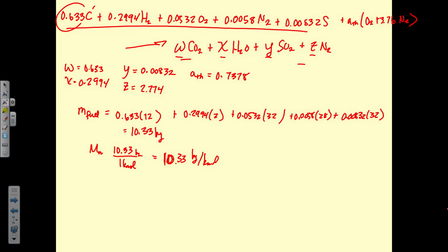Okay. So if we look at this, we can see, and if we remember from the previous slide, that all of these reactants are stable in their current forms, which means that their enthalpy value at the reference state, their H sub F value, enthalpy of formation, is equal to 0 for all of the reactants because we have carbon, hydrogen, oxygen, nitrogen, and sulfur.